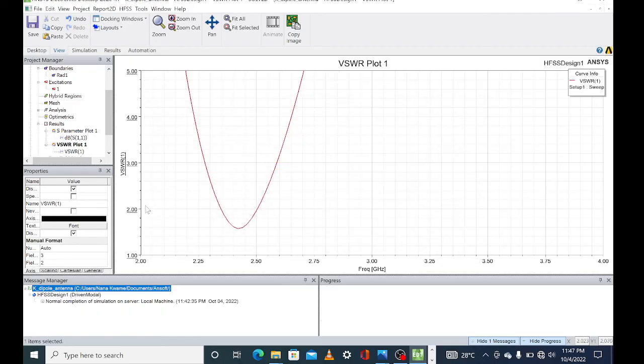Good. So this is also the standard because we know the relation between VSWR and return loss. If you want the bandwidth, we strike a line through the graph at 2. We check, we have 2.34, and on this side too, we have 2.5. So 2.5 minus 2.34 will be the bandwidth of the device, and this point will be the point where we have minimal losses.